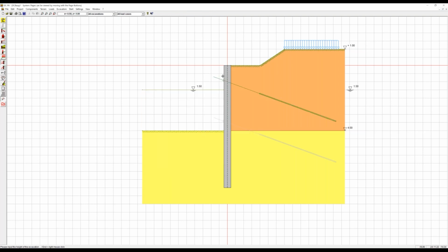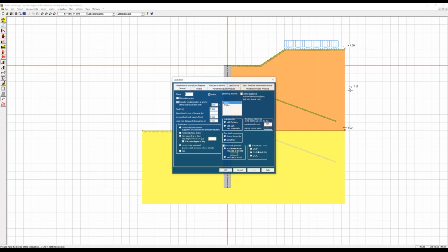So with this excavation, this anchor is now acting, it is used, therefore not shown in gray anymore. And we need the final excavation stage here, number 3, where both anchors are acting. Except if we have fixity according to Blum, we can calculate the wall with a predefined length or make an iteration to calculate the required wall length.